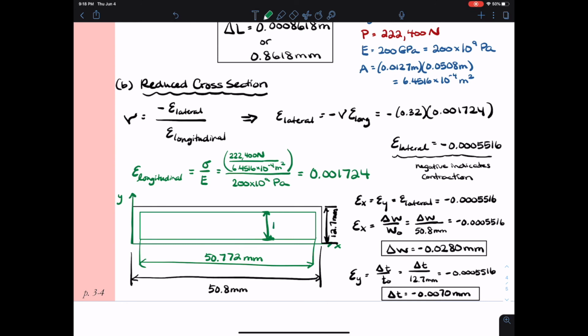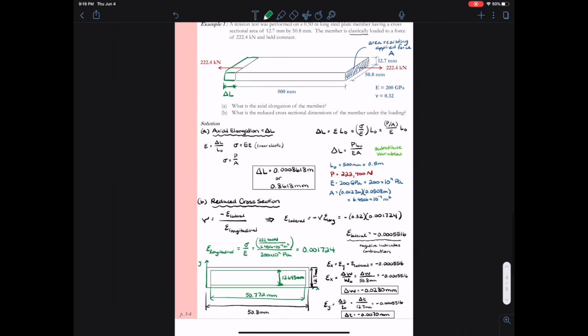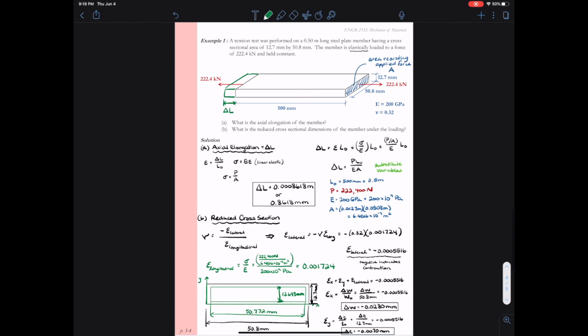Now, we could look at this in the inelastic range. Just remember, though, that back when we were calculating strain, we assumed that the strain was equal to the stress divided by Young's modulus. So that only applies in the linear elastic region. So we would have to use the stress-strain curve information if we wanted to do calculations in the plastic range, because sigma equals E epsilon would no longer apply, so we'd have to do something differently there to get our value from our graph.